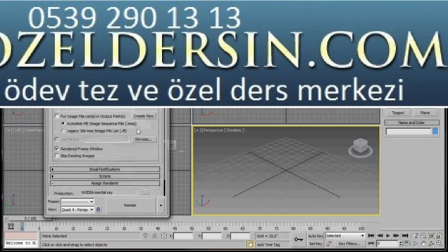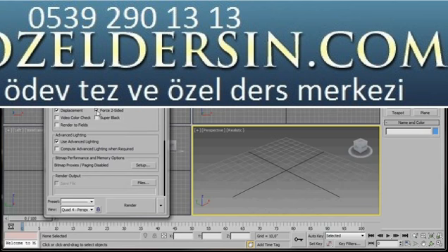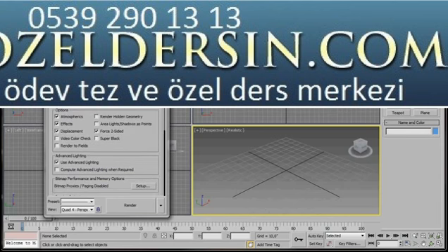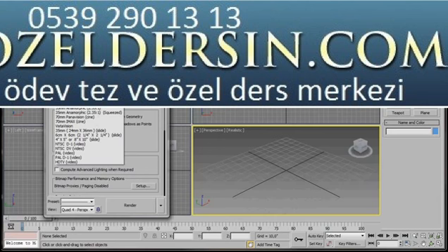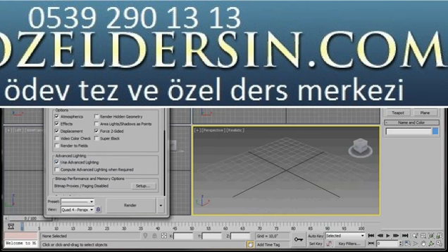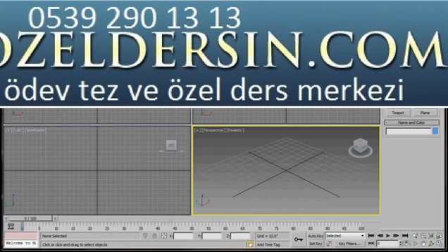Now we're just going to scroll up. I'm going to turn on Force Two-Sided, and I'll carry on to Output Size, Customize, and behind Customize I'm going to select HD TV. Now the width I'm going to set to 640 and the height to 360 for this video, but my final result I'll render out at 1280 by 720. Okay, let's close the dialog.